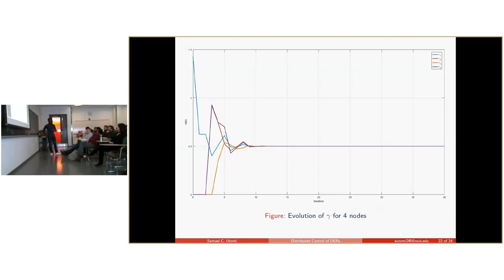I should have mentioned this earlier, but we have a robust ratio consensus. The initial ratio consensus algorithm has a problem where, if you have packet drops, there's a possibility of convergence to an inaccurate solution. So in order to make up for that, we have a robust ratio consensus which accounts for those packet drops. Instead of just taking the updated values, you sum those up accordingly so that even if you miss them at one iteration, you can always get them back in the next iteration.